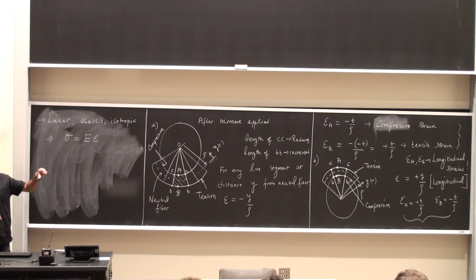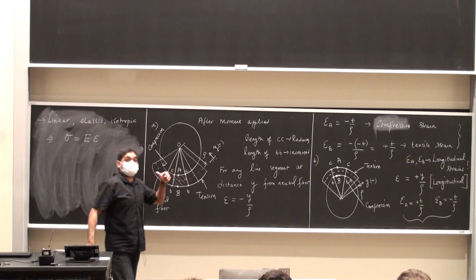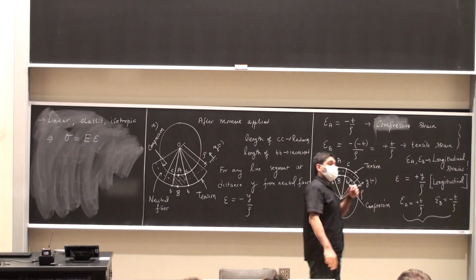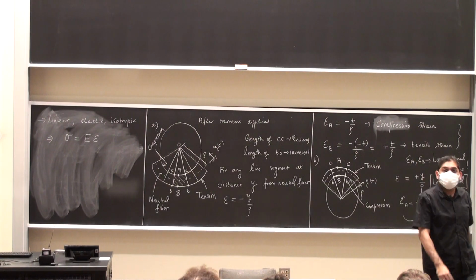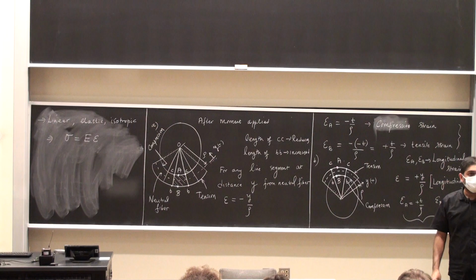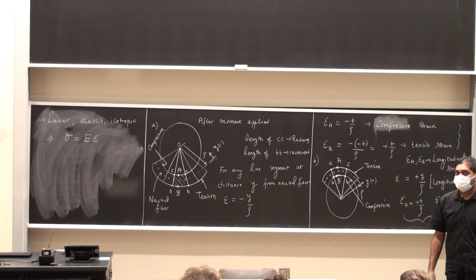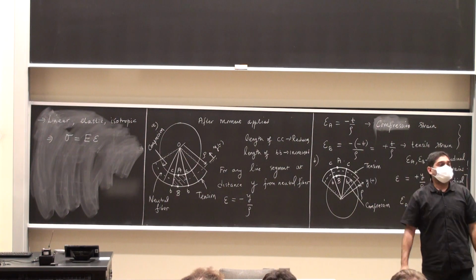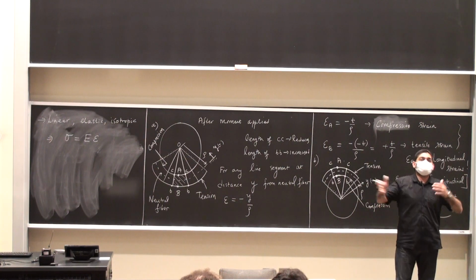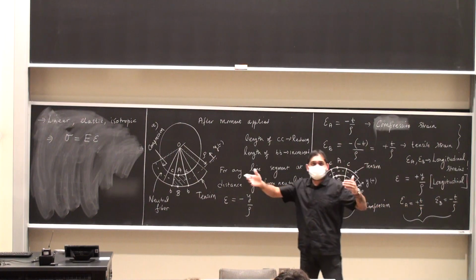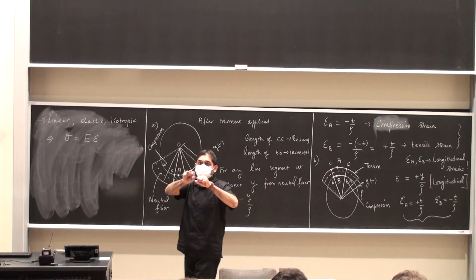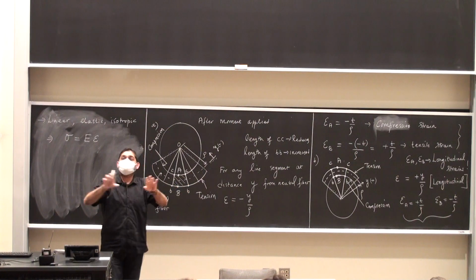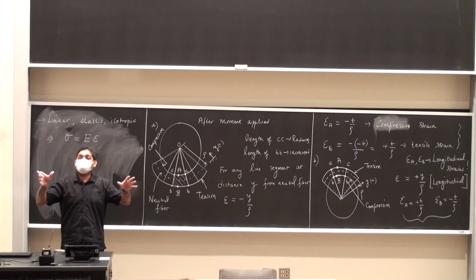If I have longitudinal strains, I'm going to have longitudinal stresses. Do you know of any other stresses that are longitudinal? Yes? Would it be normal? Normal stresses or axial stresses. You had these axial problems where you had applied load along the length of the body and you caused some stresses. Those are normal stresses.